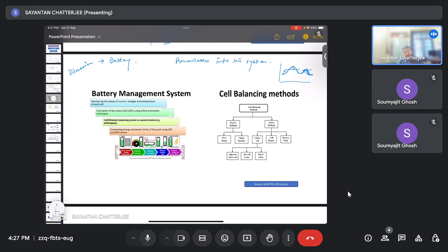Also, we can also see the conventional generation system, where we can see these alternators. So these alternators mainly deliver what we call the real power, but additionally, it has the feature to deliver inertia. It will meet demand, but it also has the feature to deliver inertia to the grid.